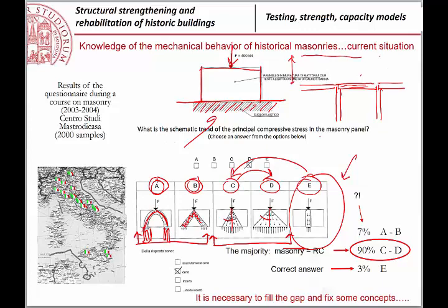And we have over the masonry a force applied here, then you have a formation of just two straight areas that are distributing the loading from the top to the columns. But of course, this is almost never the case, because the self-weight of the masonry is significant. So typically, you have the formation of an arch, as I said before.